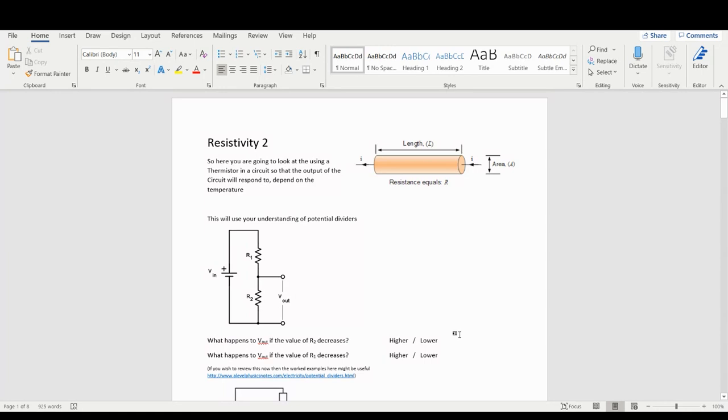Okay, so resistivity is really important because it is a material property of conductors and insulators too. For example, water has a resistivity of 1 times 10 to the 10 ohm meters, which means for a meter's worth of water, there is going to be at least 10 mega ohms worth of resistance. So it can still conduct, it's just ridiculously resistive, which means that's going to take a lot of potential away. So if you try and conduct electricity through water, the water itself is going to take a lot of the potential away because of V equals IR.